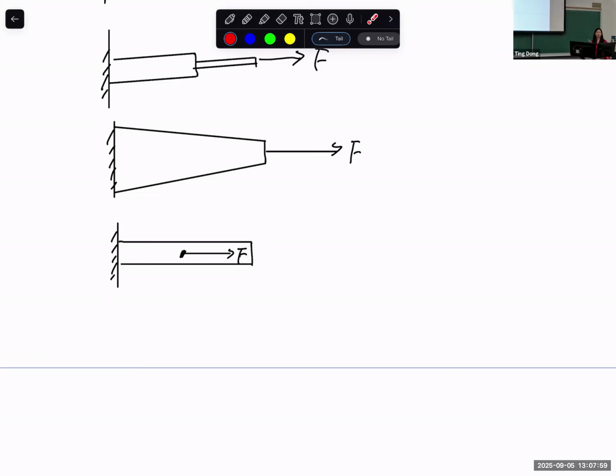So how to calculate stress in the bar? Yes, thank you. Force over area. Same as the previous step, in the previous class we calculated the internal force of the spring element, and with this internal force divided by the cross-section area, you get stress. When the internal force is positive tension, the stress is the same.